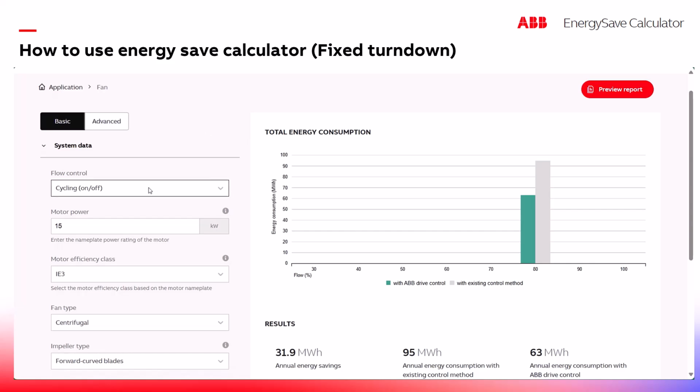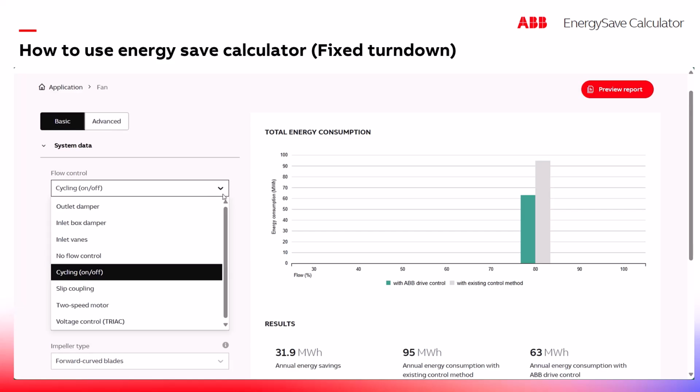The next option it's going to ask you is flow control. So how is it currently controlled? So you've got options: is it an outlet damper, inlet box damper, inlet vanes, no flow control at all, cycling on or off, slip coupling, 2-speed motor or voltage control. Some of the one I see commonly is cycling on and off. So I'm going to use this for this example, but you could use whichever one applies to your application.